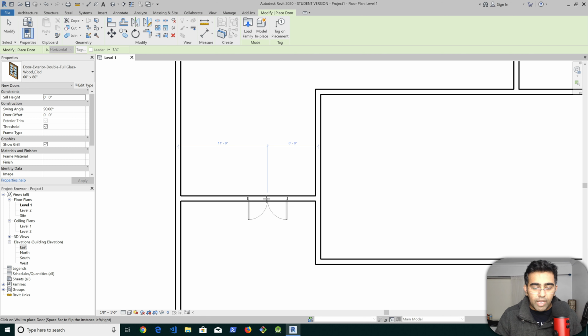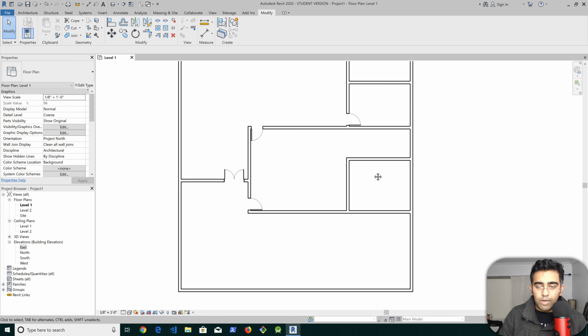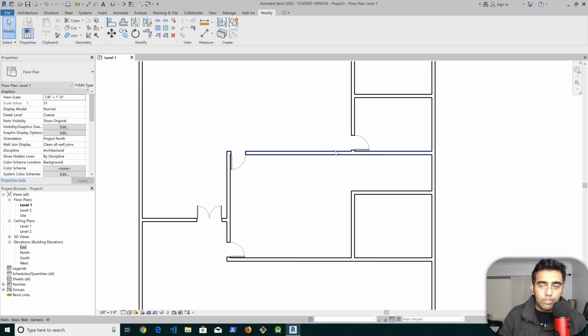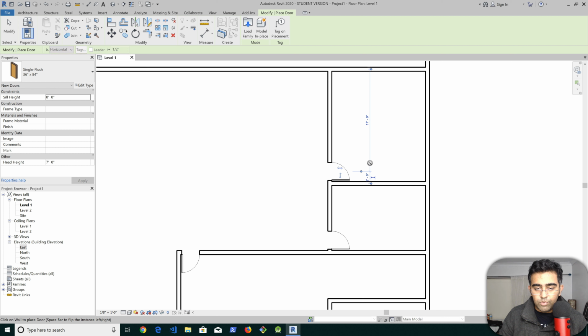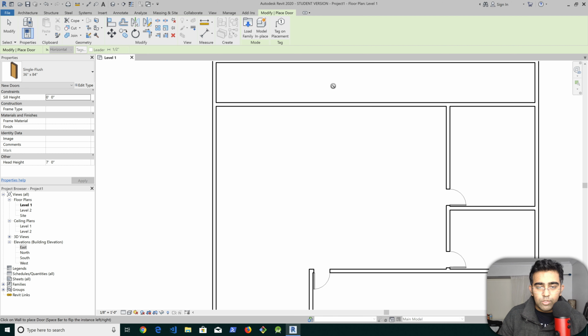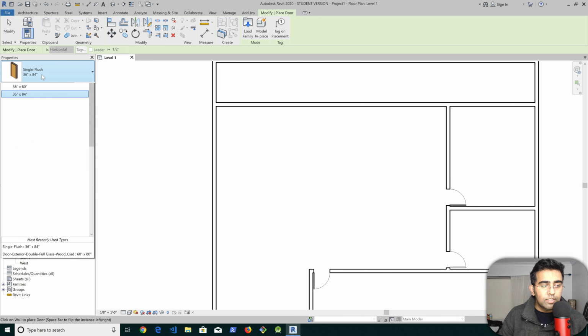It's gonna be like an attach, but we're gonna click something like this. We're gonna have a cupboard here. I'm going to use this trim and extend, select this part to get rid of that wall. Here we're gonna put some interior, like dressing, some sort of interior. And then here we need a door again, guys. Let's go to the architecture tab, click on door, and I'm gonna just click here for the door. All right, to get out, we can click on this properties and get the bigger door.